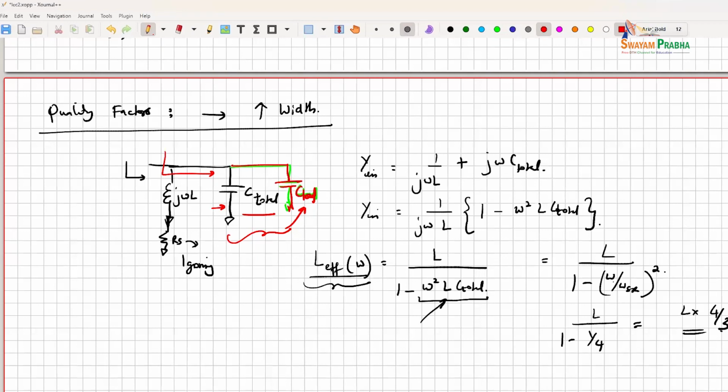So you could easily see people operating inductors at 70% of their self-resonance frequency if you take the inductor standalone. But that's because the load is already accounting for the inductor capacitance. So then you're okay with the design. In fact, this happens in transformers quite often. So it isn't a bad thing that this capacitance exists.